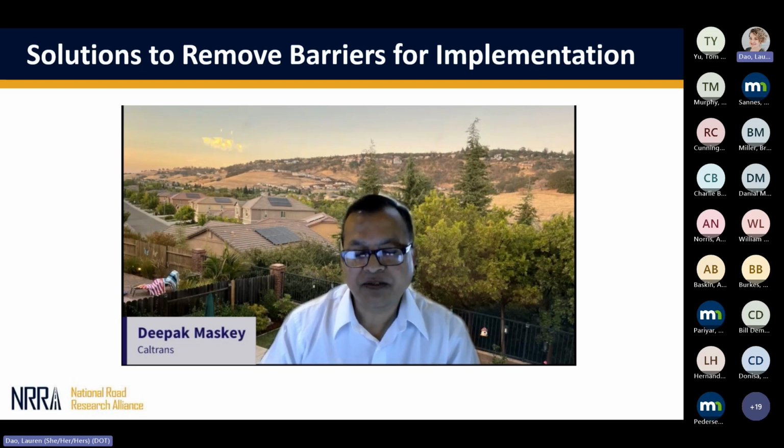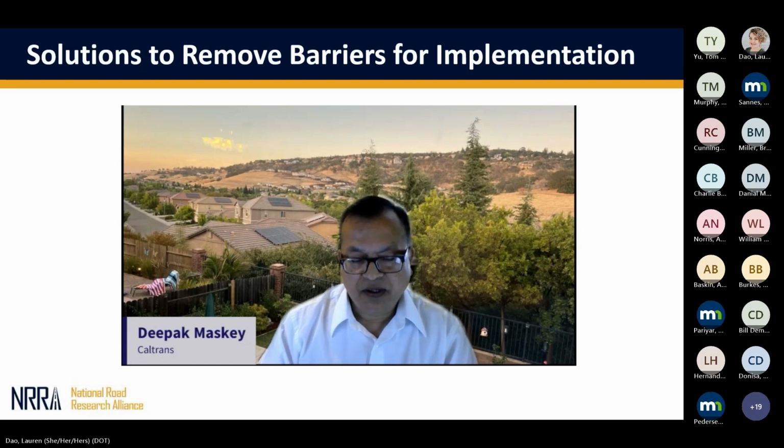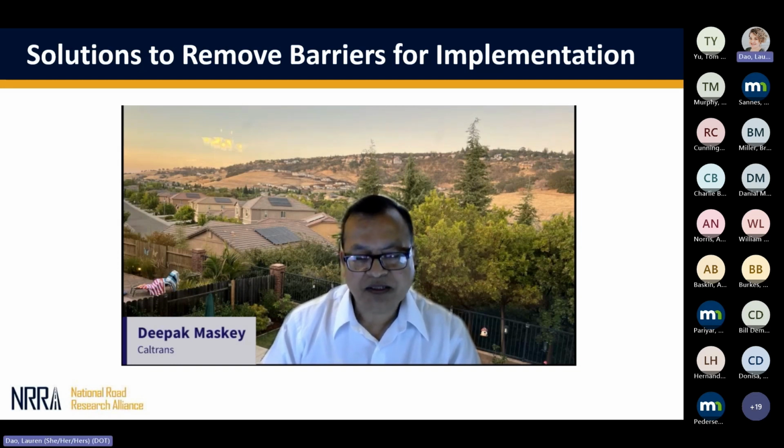We need a very stable base, a really durable base. If you don't have a base or foundation, then whatever you put your pavement on is not going to last. So we must have a kind of specification, a kind of guidelines for the design of really durable, long-lasting bases, even though its influence is not captured in concrete pavement, because the way concrete pavement is designed is based on cracking. So that is the reason.